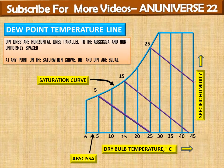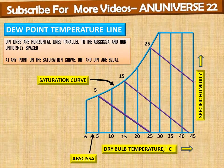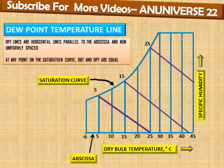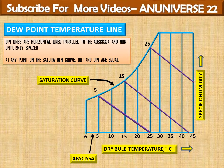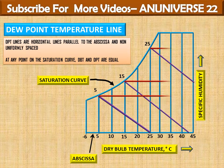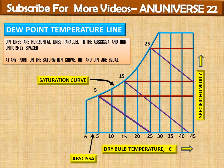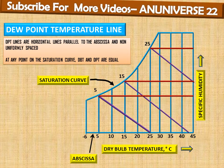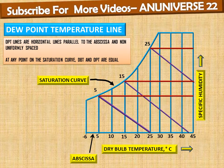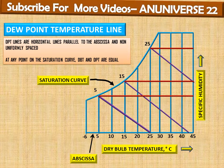At some points on the saturation curve, DBT, the dry bulb temperature, and DPT, the dew point temperature, are equal. So these red lines show the dew point temperature line, and these are non-uniformly spaced.